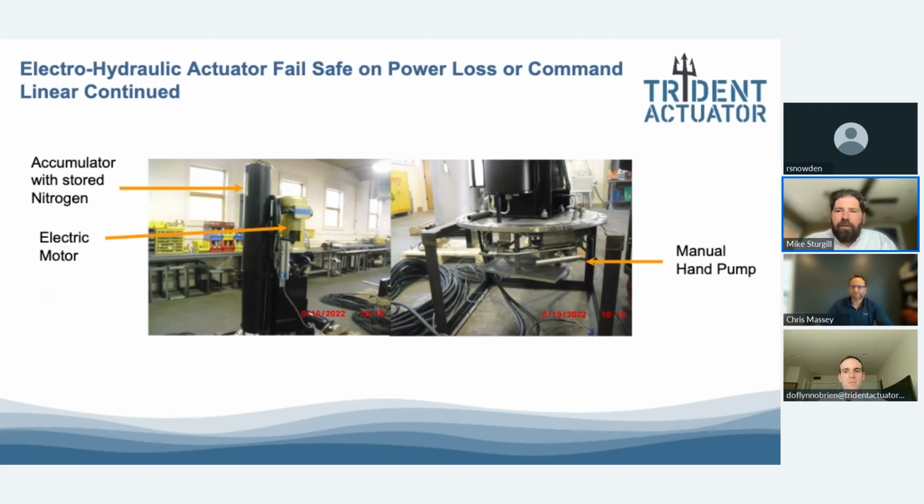One thing to know is every time you start one of our actuators that is fail safe, initially the stored energy in the accumulator has to charge. So you cannot operate until the stored energy is charged. Once it's charged, you have full operation of the actuator and the stored energy in the event of power loss, or on command, as some customers want it that way for small power blips, so they don't lose basically closing or opening a gate or valve. But that's it for underneath our stainless steel enclosures.